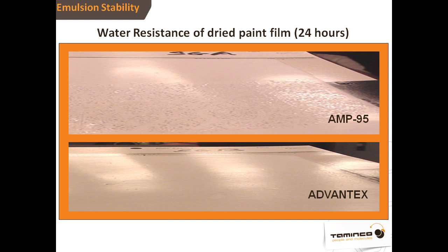And one way to rationalize this is to take a look microscopically and to note that this film is less permeable, more coherent. And that could be a result of enhanced colloid stability, of enhanced emulsion stability, of a reduction in the interfacial tension between the different phases of this coating. So if it's less porous, you can lay a wet paper towel on top of it and not get all this boiling and bubbling that's just a result of the water entering the film through cracks and other porous openings.